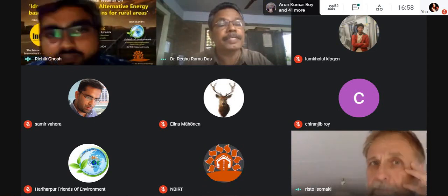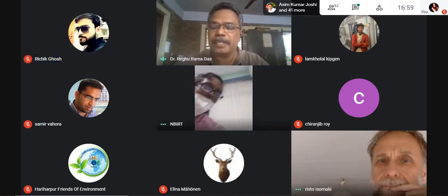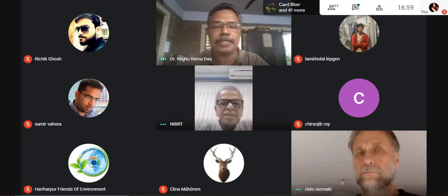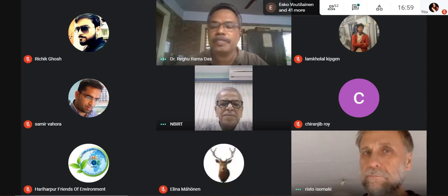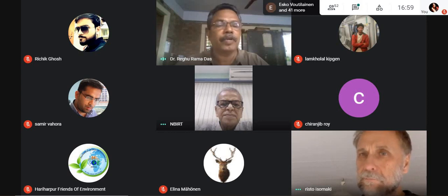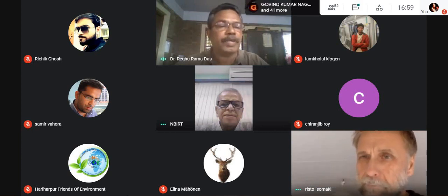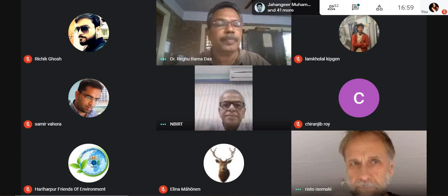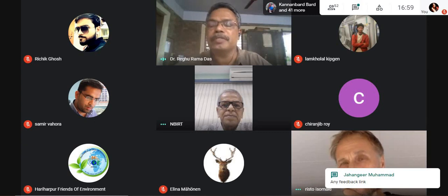Issues, sir. No, that is what I have presented. The main problem with the existing dryer is the high humidity in the area. After drying, in the next day morning, we have to remove the product every day. Otherwise, in the next day morning, there is high humidity and the product again gets more moisture content. Then gradually it has a fungus attack and the product gets damaged. That is why we are trying to develop a solar dryer with better airflow. So humidity is the main problem we are facing. The other dryers available locally are very expensive, which these people cannot afford.